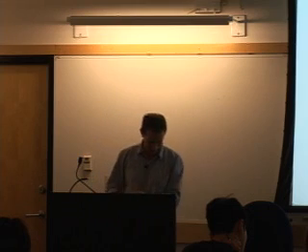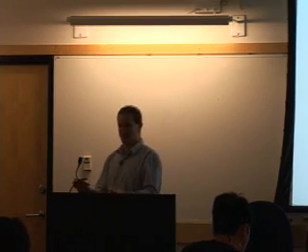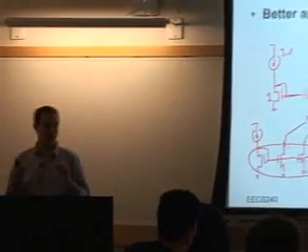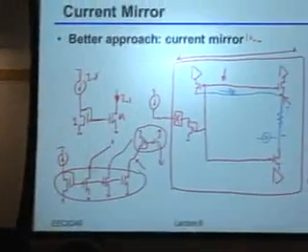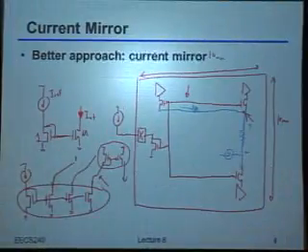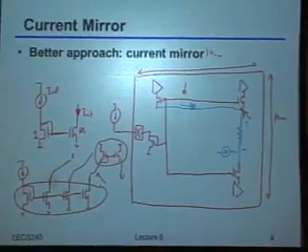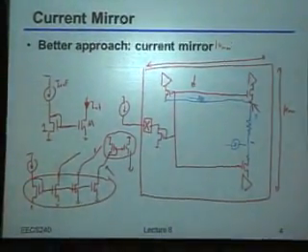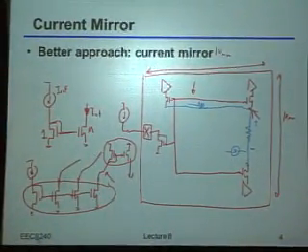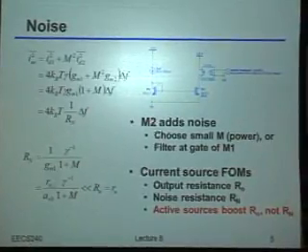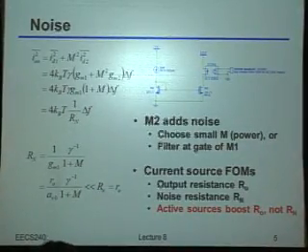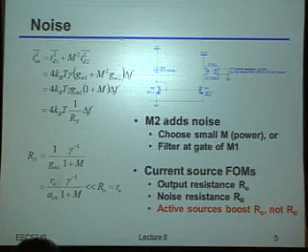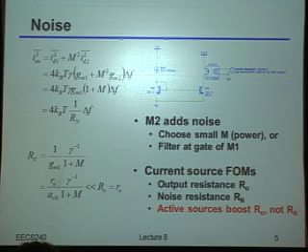Okay, so again, keep this one in mind because the current distribution or bias voltage distribution problem is a very common problem, so do it the right way. In other words, always route the current, not the voltage. Okay? Okay. So now that we've talked about that, now we can start thinking about another new parameter that we've now been exposed to in 240, which is how much noise will these current sources really be adding at their output.